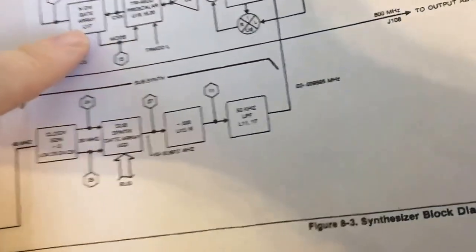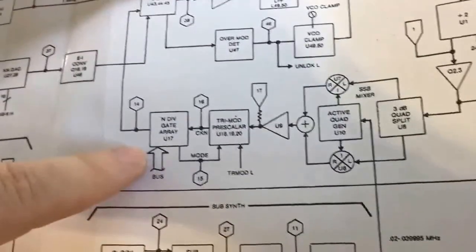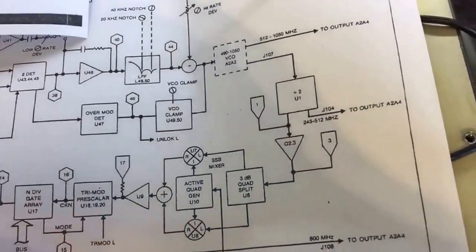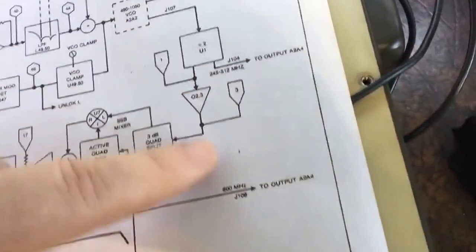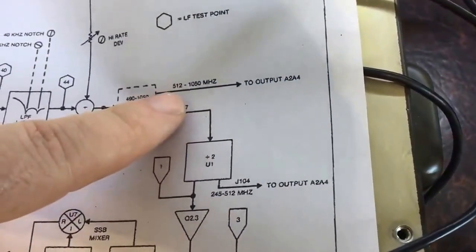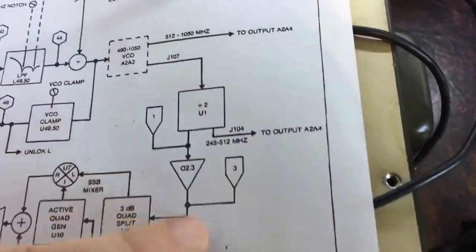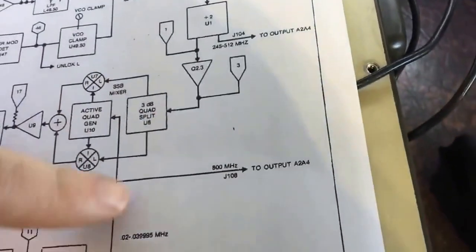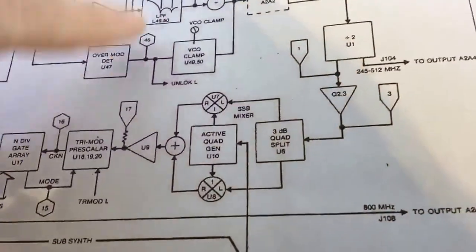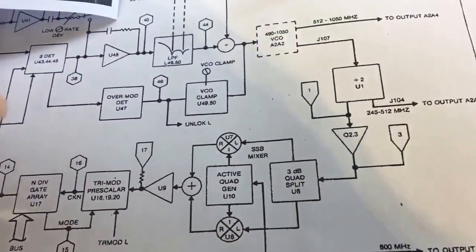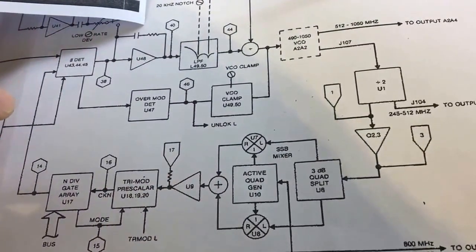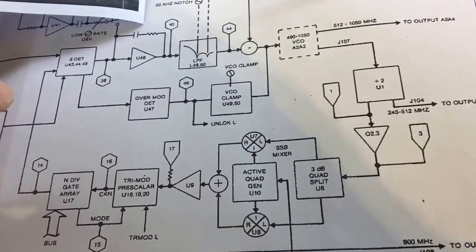And there's that gate array at U17, which I'm suspecting, just there. You see, it's all interrelated, and all the bands are wrong. So let's see, this band here is wrong. This band here is wrong. It doesn't actually mention the lower band. So I don't think it's just anything in this section, because that all seems to be the same across all the bands. It's doing the same full right across that 20 MHz shift. It's not changing by much or anything.